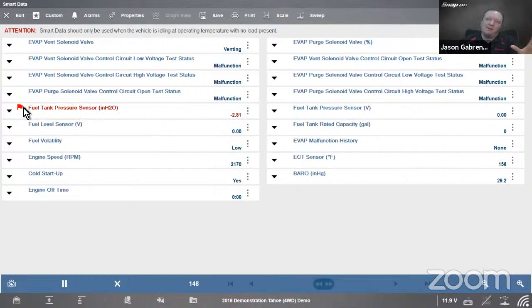So high and low. If it ever goes outside of those values, it'll turn the flag red. It'll turn the PID name red. And we can also monitor the data. If the data is red, it's out of spec. If it's blue, then it went back into spec, but the flag stays red. So right here, you see how it went blue. That means it went back into spec.